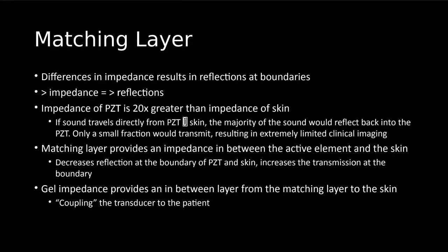So the impedance of the piezoelectric material, or the active element or crystal, is 20 times greater than the impedance of the skin. So that's a pretty drastic boundary for that sound wave to have to travel through, and it can't. So that's why it just reflects itself right back. So if sound travels directly from the PZT to the skin, the majority of that sound wave is going to reflect back into the PZT. Only a small fraction would transmit, resulting in extremely limited clinical imaging, and that's why we're not getting any type of diagnostic picture.